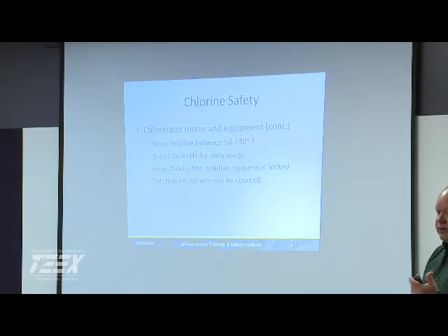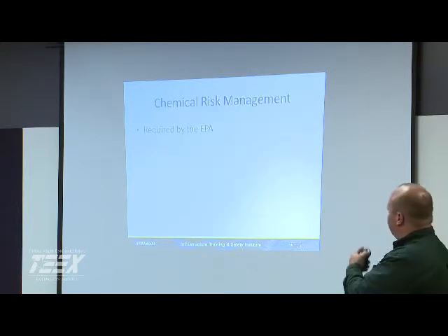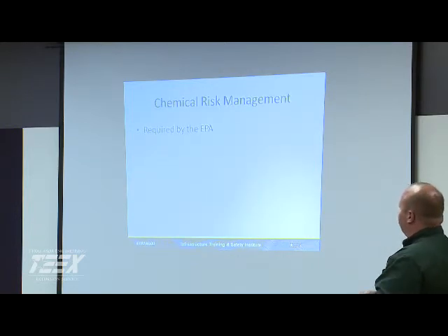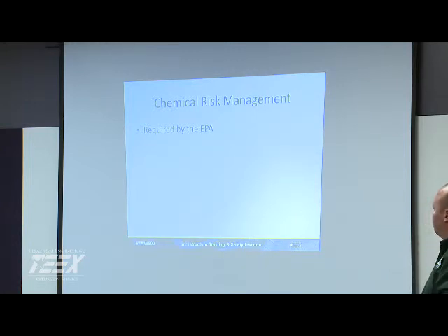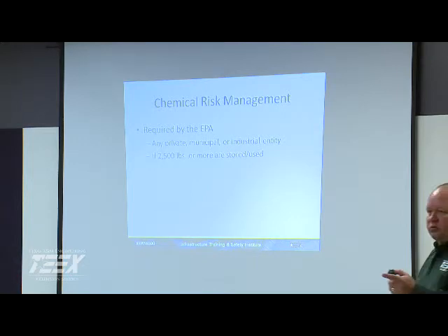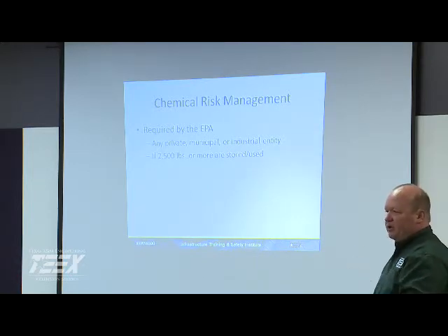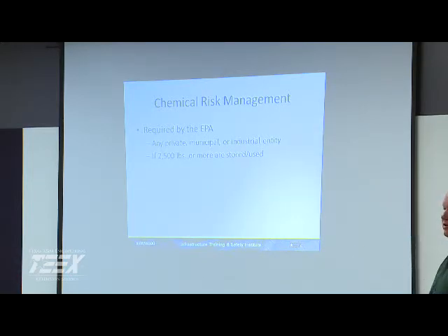If you are running hypochlorite, you want to make sure it's covered. If you can have it protected from the sun, because UV is going to degrade it. Do y'all have y'all's inside of a building? So that's important. If you have more than a certain amount, you're going to have to fall under the risk management program. Luckily, I don't think y'all are above the 2,500. If you don't have to be, don't, because it's a lot of extra work, a lot of extra headaches.